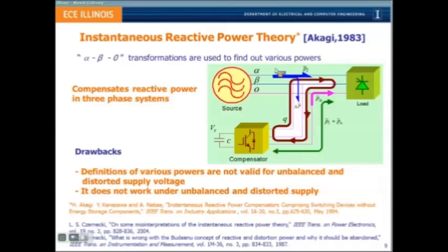It studies three-phase time-varying sinusoidal components as a two-phase system. We call this a stationary reference frame transformation when we analyze machines. Every component becomes simpler in analysis when you do this transformation. Okay, let's look at this picture a little later.